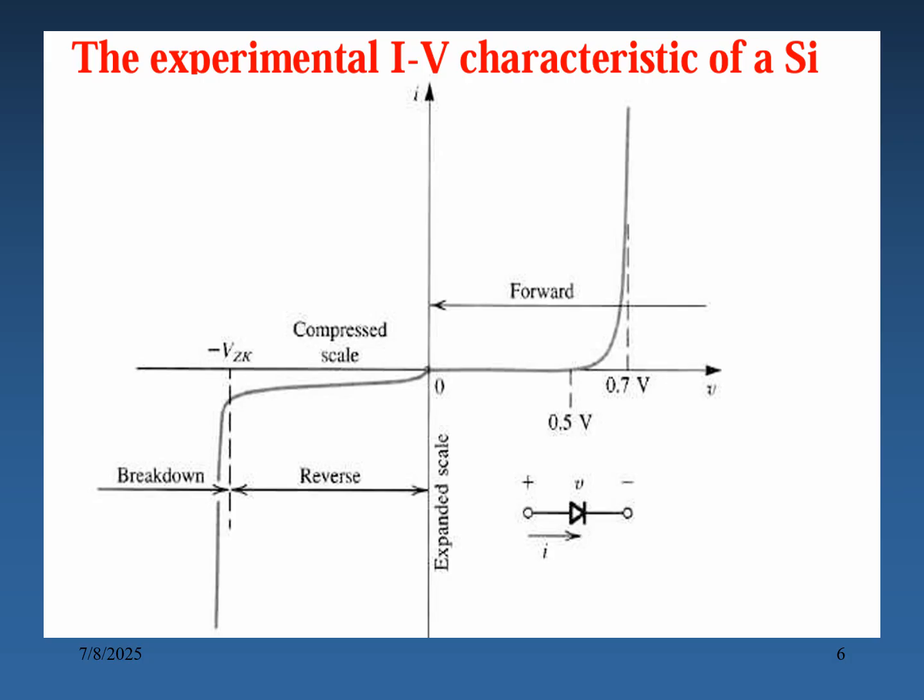In reverse bias, this curve is due to the reverse saturation current, due to the movement of the minority charge carriers. The x-axis is the applied voltage in volts, forward applied voltage, and the y-axis is the positive current through the diode. In forward bias it is in milliamperes. In reverse bias the applied voltage is negative. After a certain applied voltage, the junction breaks down. Here in reverse bias a breakdown occurs.